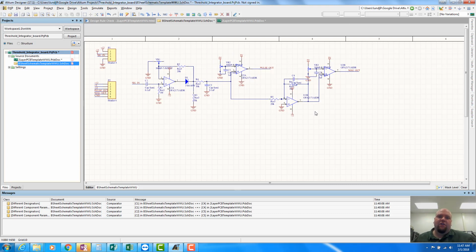The second signal is sort of a pulse width modulation, which tells you the amplitude of your signal, and the first pulse out here is just telling you, do I have a signal or do I not have a signal? And then there's digital processing later on that's going to take these pulses and interpret them to mean various things. So we have to route this, but I want to point out one thing that I did here.